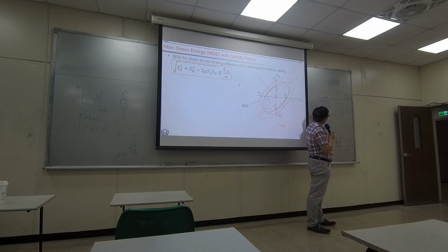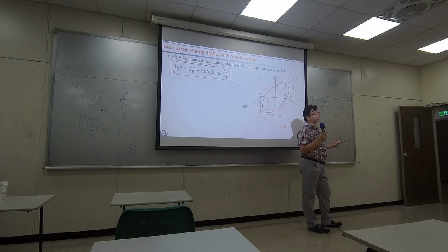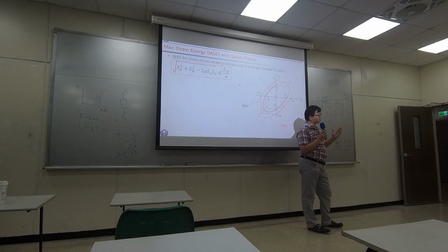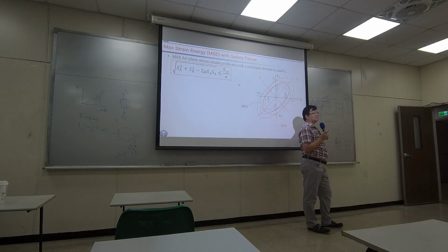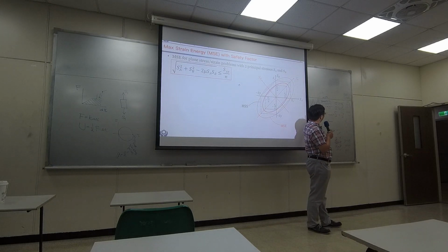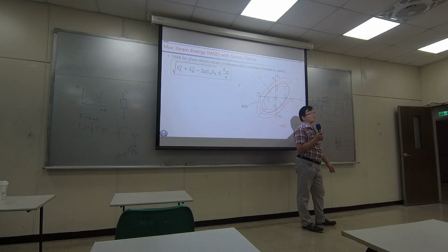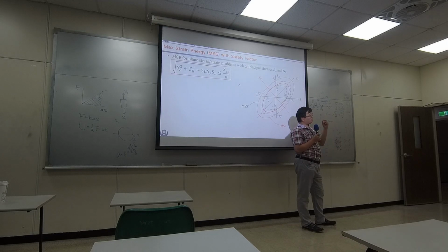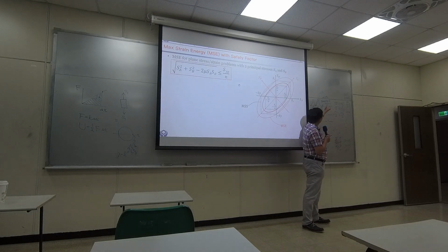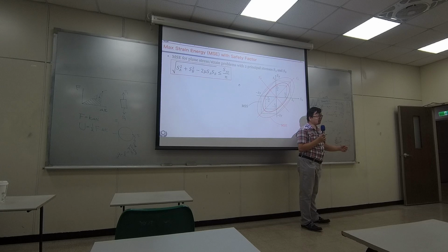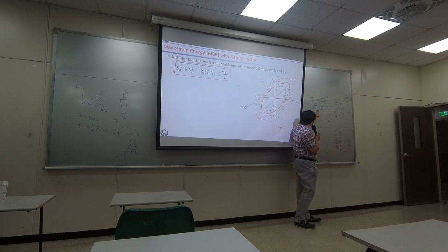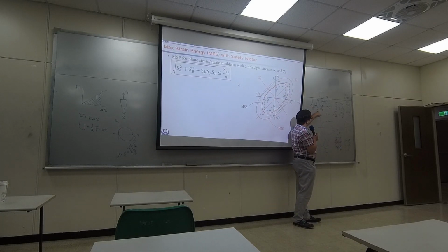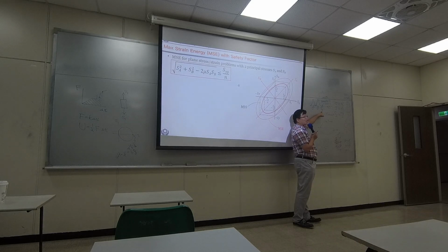If you do face this kind of situation, that means when you have 1,000 pieces, 20% of the pieces will fail, if this is drawn precisely. Okay, so design of mechanical components cares about failure rate, reliability. That's why they don't want this mean value to be too close to the design limit. They want to keep a gap.